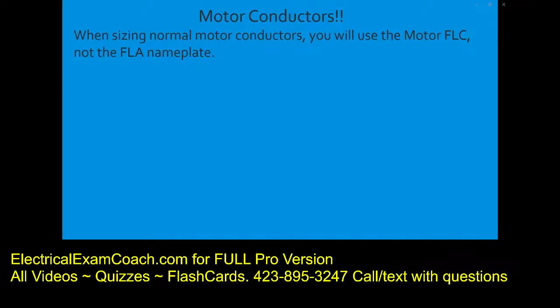Remember how we've learned previously that every piece of equipment has a nameplate, and it'll say things like what voltage the equipment is and what the amperage is. Well, on motors, they'll typically stamp an amperage, but that's the FLA. So when we're sizing normal motor conductors, we're actually going to use the FLC, and I'm getting ready to teach you how to find that value. We're going to find these values in table 430.248, and that's for single phase. It's on page 321 of the 2017 or page 332 of the 2020.